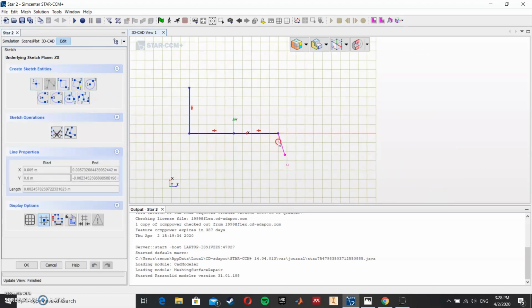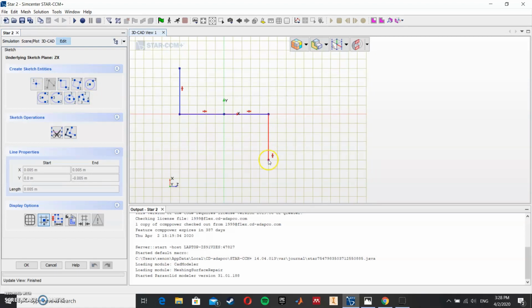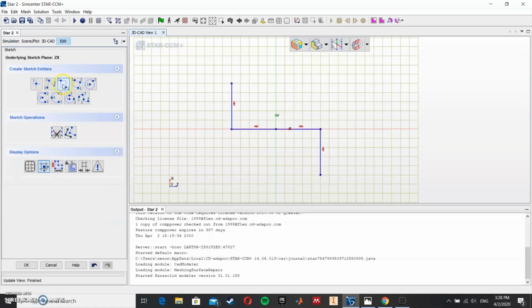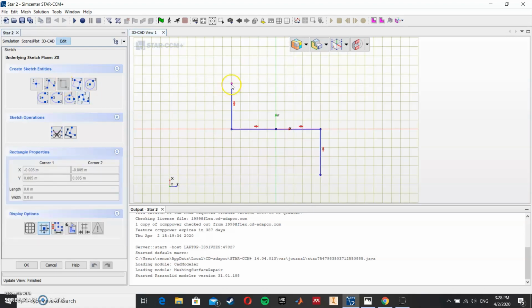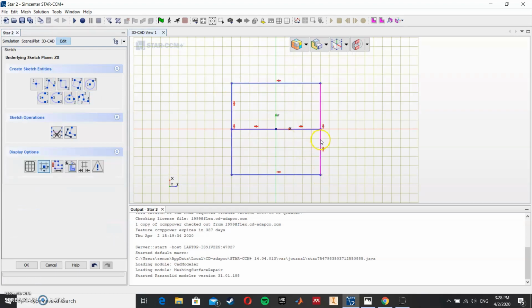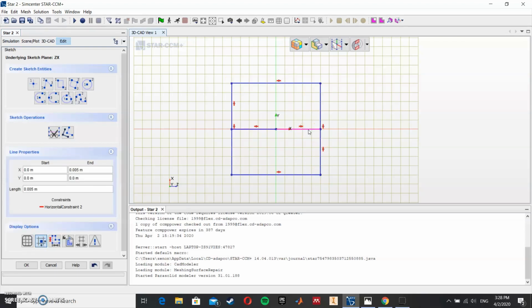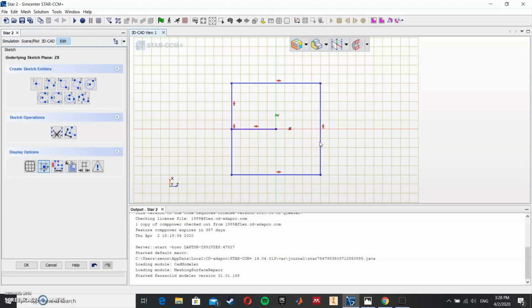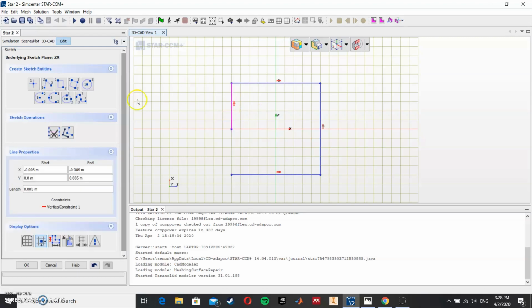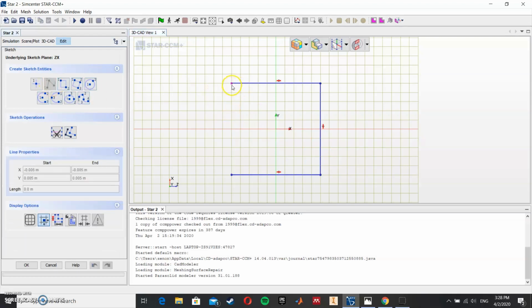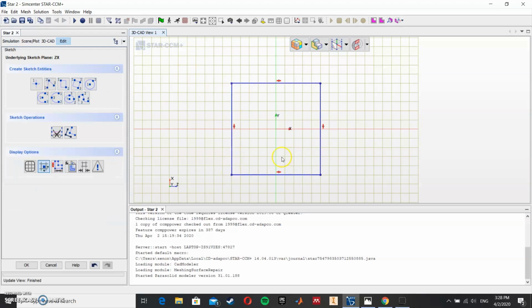So yeah, that's that. So 5 millimeters there. You can select this, okay, and then you can just do that. It's easier, well, this way it was easier for me. You can just do it line by line. Doesn't matter. What's bad about this way is that you have to delete the lines. Otherwise, extrusion will not happen. The system will give an error. So you say okay, that's our first sketch.